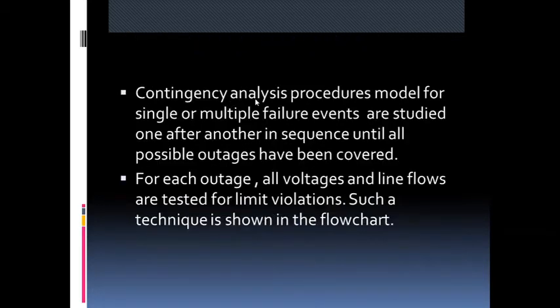So these contingency analysis procedures model single or multiple failure events, which are studied one after another. These faults will be simulated one after another and the analysis will be done until all the possible outages have been covered. For each outage, all voltages and line flows are tested for limit violations. Such a technique is shown in the flow chart.